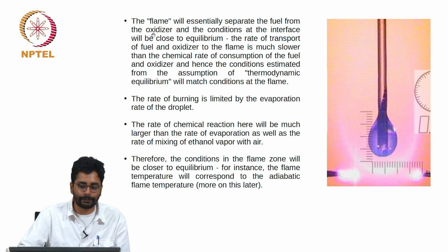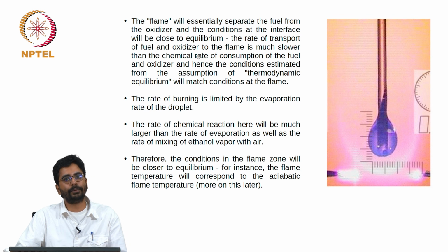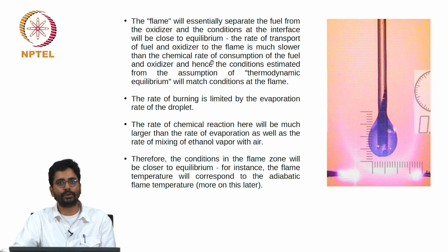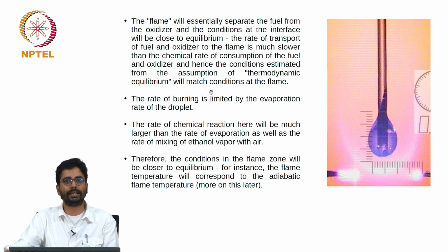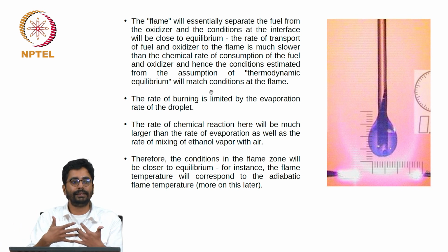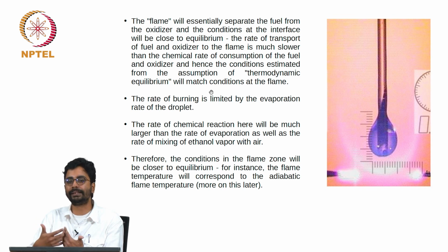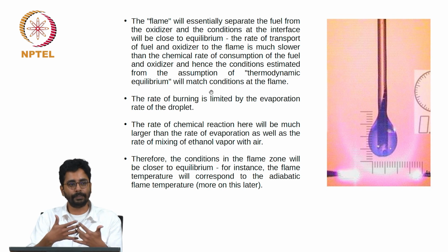Here it separates the fuel from the oxidizer, and the conditions at the interface will be close to equilibrium. The rate of transport of fuel and oxidizer to the flame is much slower than the chemical rate of consumption of the fuel and oxidizer, and hence the conditions estimated from the assumption of thermodynamic equilibrium will match conditions at the flame. So, as far as the chemical state and the thermodynamic state are concerned, you can assume equilibrium.